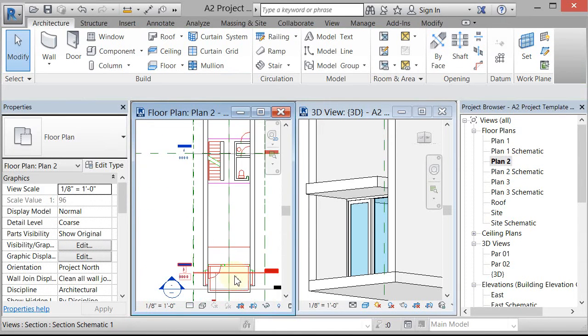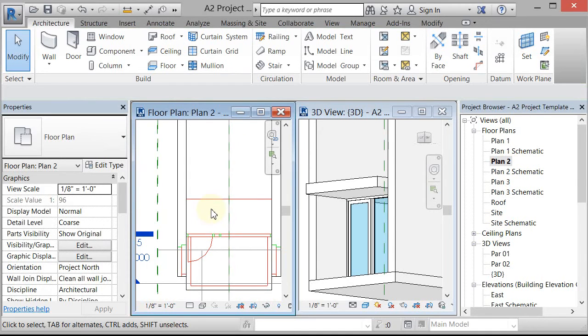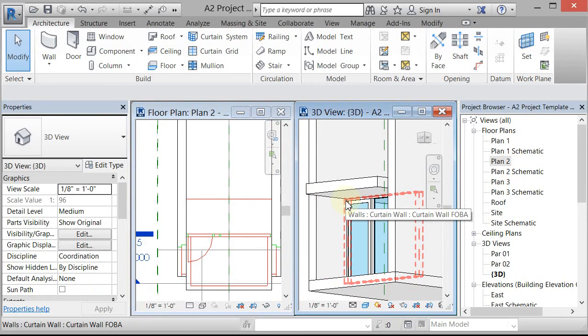And looks like we have another curtain wall here. Since we have a similar curtain wall on the ground floor, we can actually copy and paste it up. So if I come in and pick the curtain wall system, which you can pick different pieces of, but we want the entire system, you hover around the edge of it and left click.